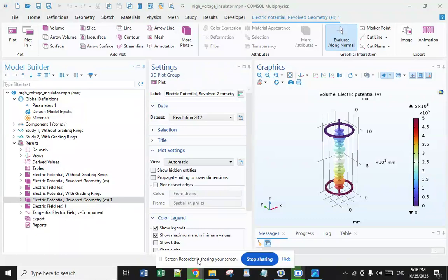The proper selection of the insulator type and design depends on several factors including line voltage, electrical conductor, loading, and environmental conditions. The main characteristics of high voltage insulators include dielectric and mechanical strength, resistance to contamination, thermal stability, electrical insulation, durability, and ease of installation and maintenance.